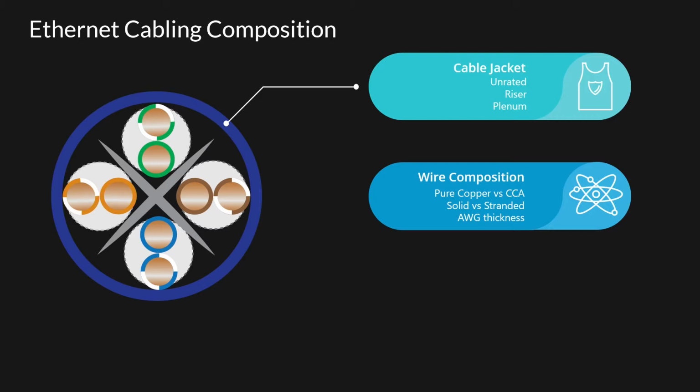And there are a lot of things that run on power over Ethernet. If you put security cameras in, for instance, power over Ethernet right away. So you got to worry about that. Make sure you get pure copper. Don't get tricked. The other thing you need to worry about, and it's not so much a trick, there are